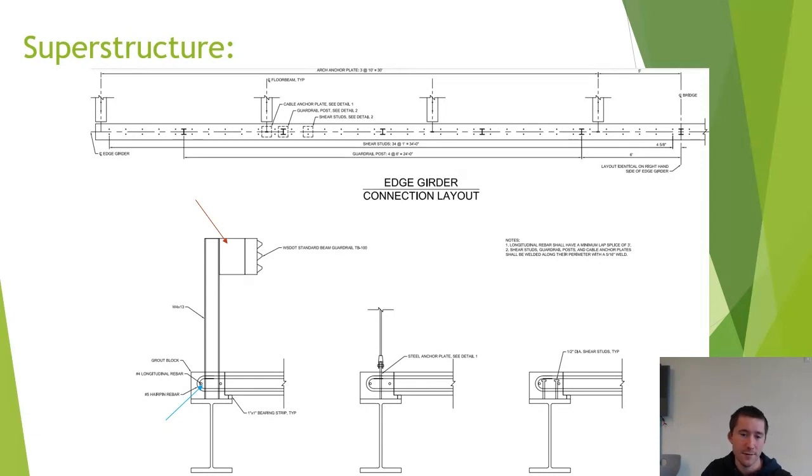Notice at the blue arrow, the longitudinal rebar to resist grout shrinkage and reinforce the connections is drawn in to confirm that everything fits. At the red arrow, the guardrail will be extended out by a wood block to allow clearance between the guardrail and the hanging cables and arches. This method of guardrail was chosen for its reduced weight in comparison to a concrete weighted barrier that could go further inward to give greater clearance, but the steel post method was easier to construct, it seemed.